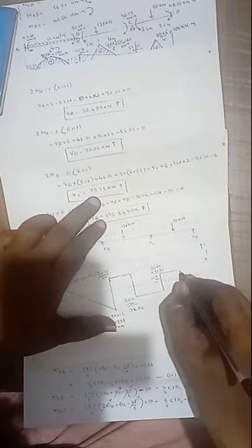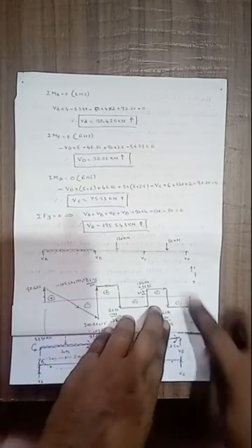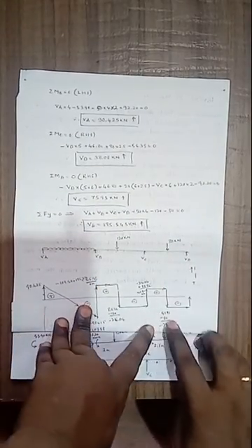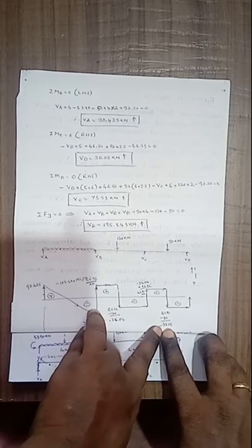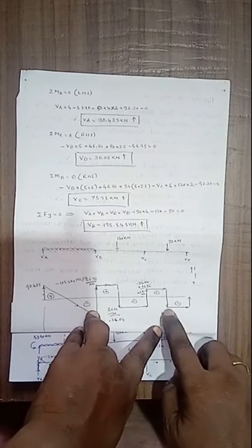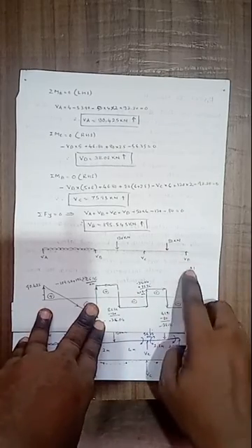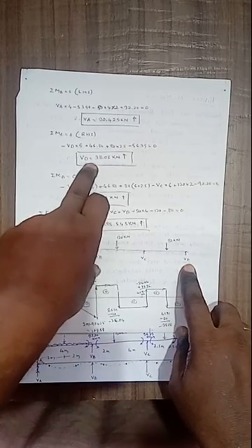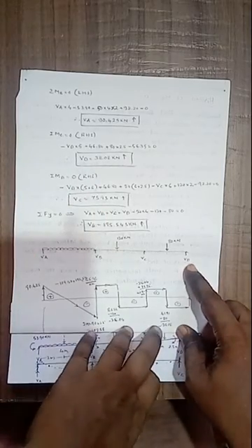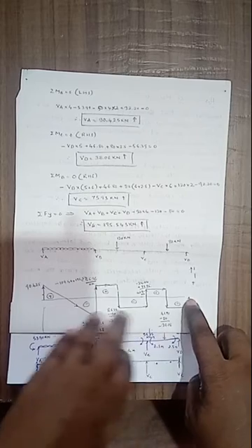Then from this point to this point, there is no load. Here there is a load of 80 kilonewton. Then again 41.91 minus 80. The shear force ordinate below this point load in span CD is 41.91 minus 80, that is minus 38.08. Then here there is no load in between 80 kilonewton and this support, then this remains constant. At support there is a support reaction VD, that is minus 38.08 plus 38.08, that becomes 0.